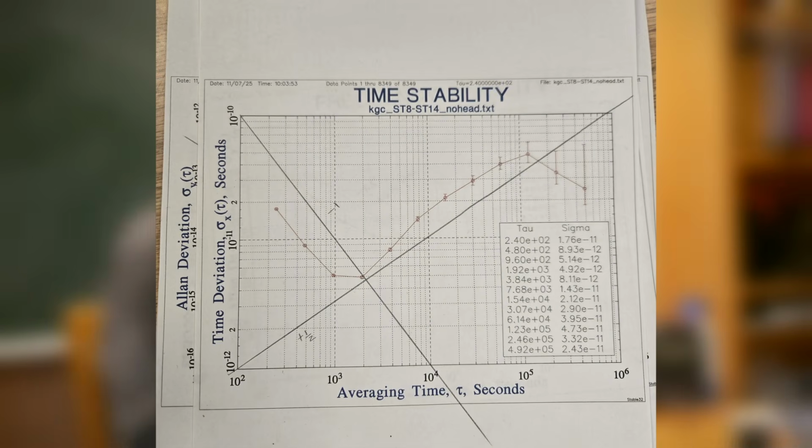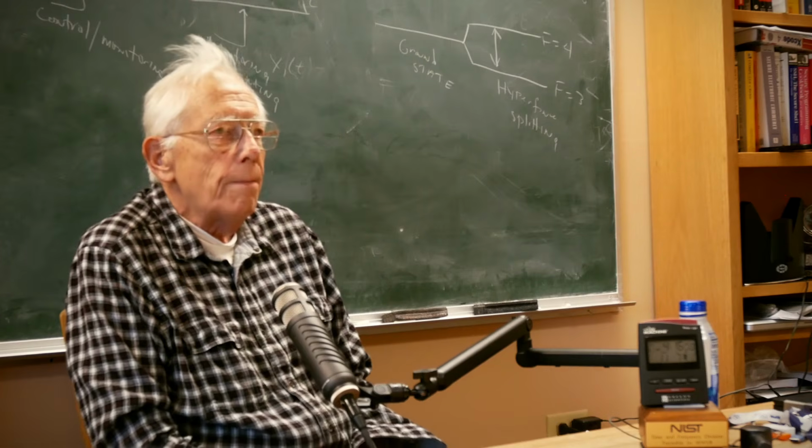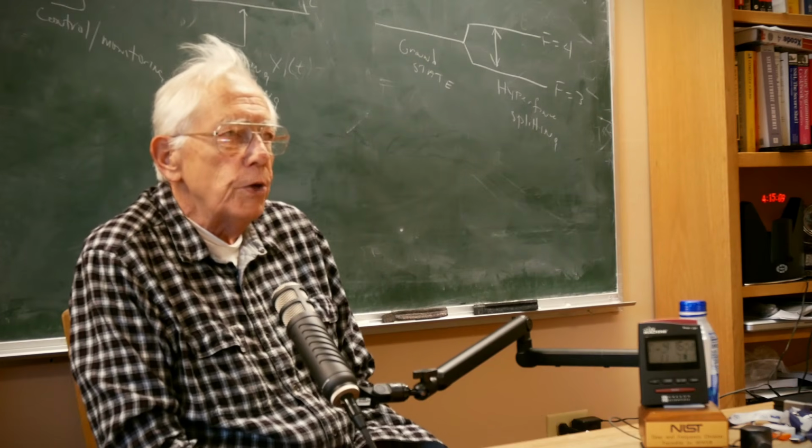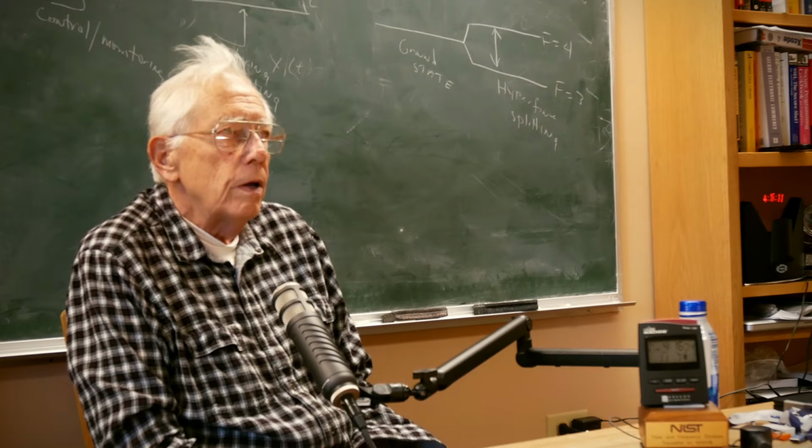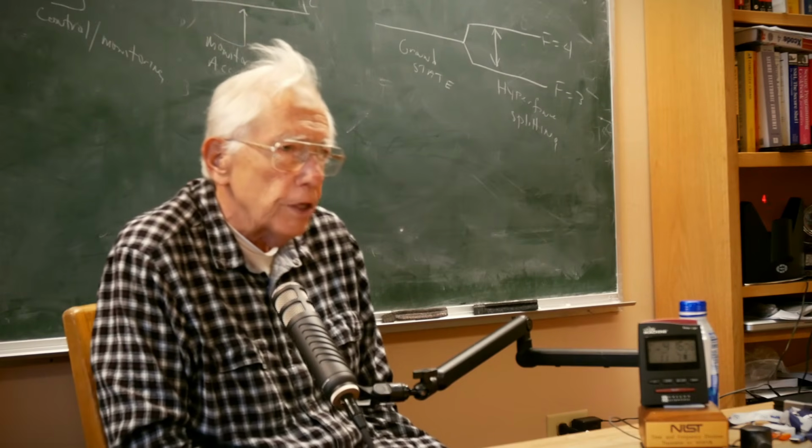The answer is you have frequency stability of the clocks and time stability of clocks, and you have different clocks, and when you have an ensemble of clocks, you try and model the behavior. I mean, that's just called the Allan variance. It's just a way of doing it, but conceptually you have an ensemble of clocks that don't agree with each other.